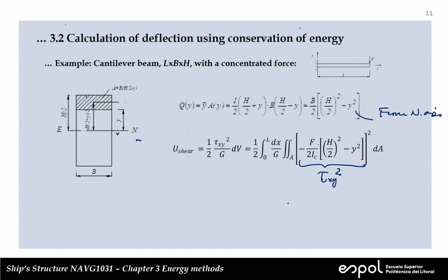So we have b here in the denominator that has been canceled, and that's the inertia. Again, the force is a constant, inertia is a constant, and we can integrate this. We have to be careful because dA is equal to b dy. So this is constant, we can take that out, and for the dy, you have dependence here, so we have to integrate.